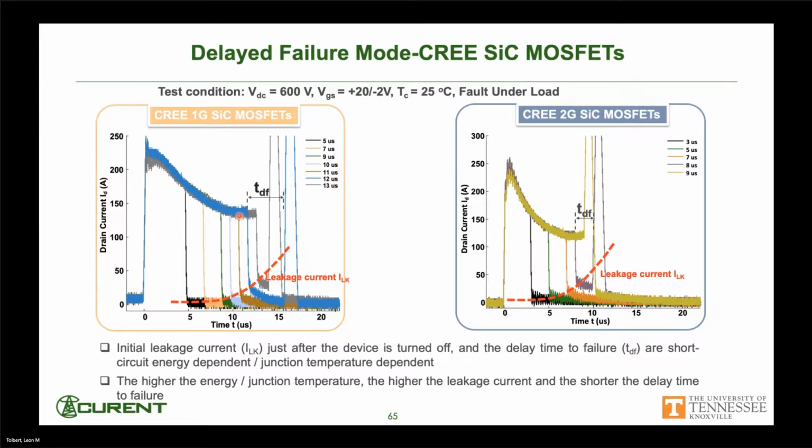Same thing with 13 microseconds. It failed, but failed more quickly. So that's what's referred to as the delayed failure, meaning you ran your short circuit current through it, you turned it off, but just that heat, it took a little bit until it reached something and damaged something.